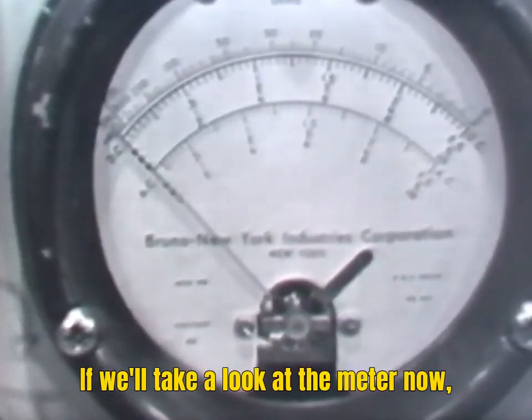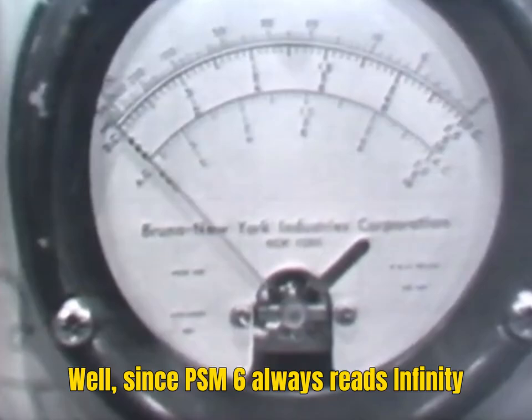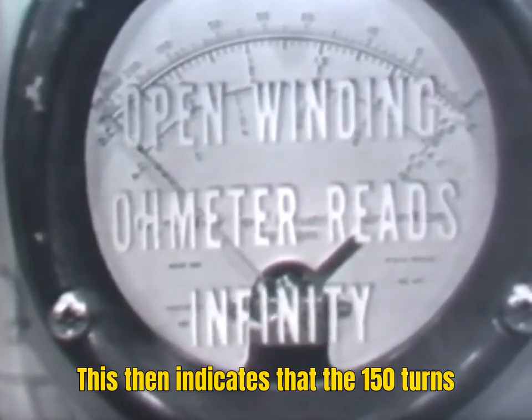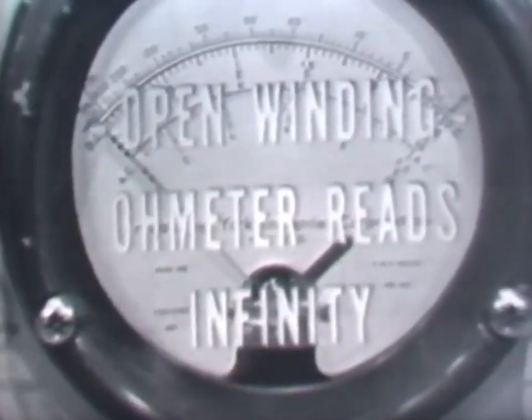If we take a look at the meter now, we'll see that it reads infinity. Well, since the PSM6 always reads infinity for an open, this then indicates that the 150 turns winding, the one I'm now measuring, must be the open winding.